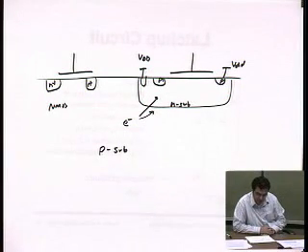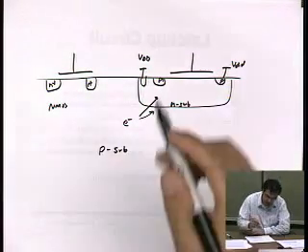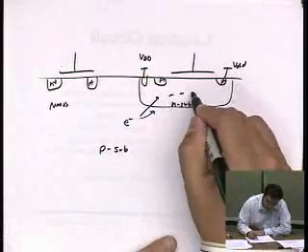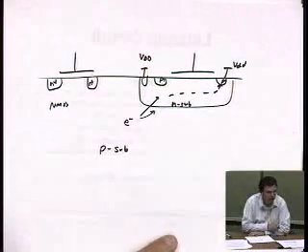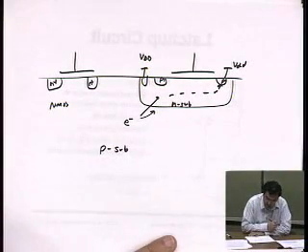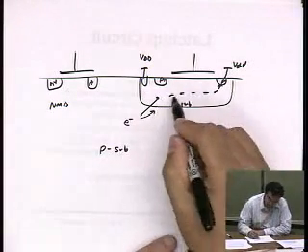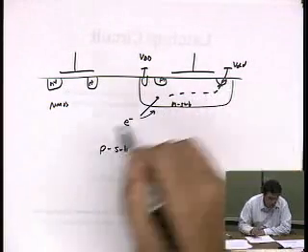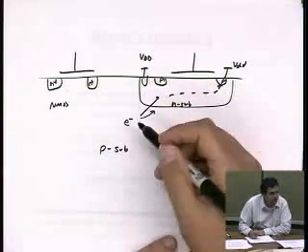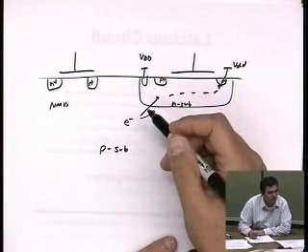And so what happens? Because you're an electron, there's a very good place for you to go, right? You can go to VDD. And in the process of this electron traveling into VDD, because this is a resistive material, there's going to be a voltage drop developed across this material, right?